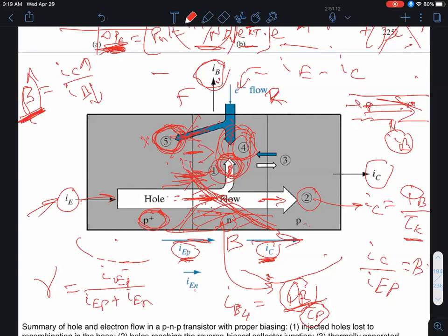All right. Now we haven't really gone through the details of that, but it'll turn out the transit time is related to the diffusion length squared, Lp squared, divided by the base width. I didn't prove that, but we can kind of take that for granted. Depending on the diffusion coefficient and how narrow the base is, that'll determine how long it takes on average for the carrier to diffuse across. That's known as your transit time.